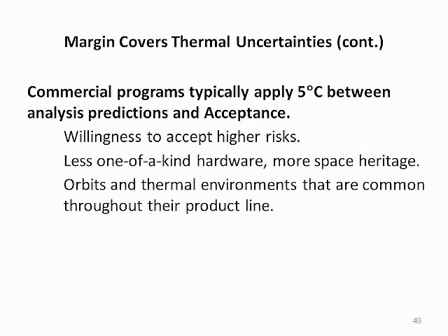Commercial programs typically apply 5C margin between analysis predictions and acceptance. In the commercial environment, customers tend to see spacecraft as a commodity, with price being of greatest importance. They're willing to accept higher risks to minimize costs. Commercial programs also tend to use standardized spacecraft which have less one-of-a-kind hardware, more spaceflight heritage, fewer components, and are flown in the same orbits and environments. It is not uncommon for commercial satellite manufacturers to have flown dozens of similar spacecraft over periods measured in decades.